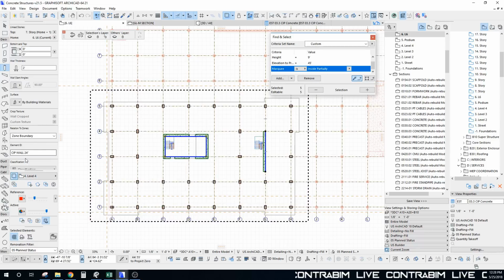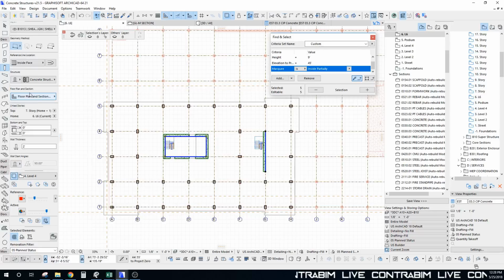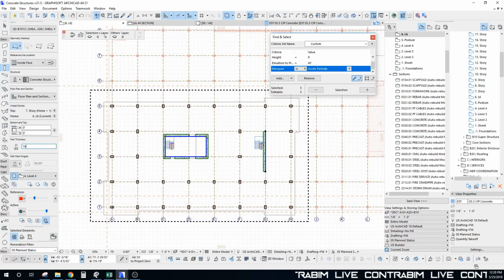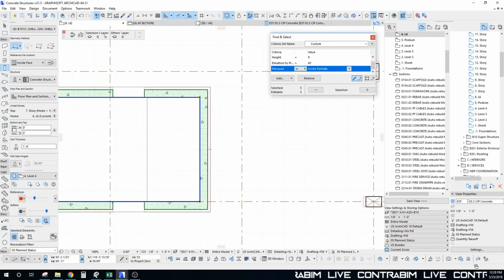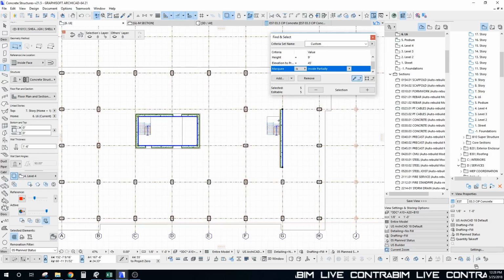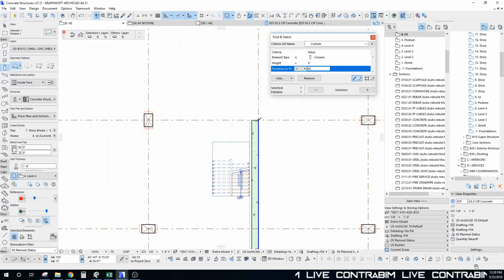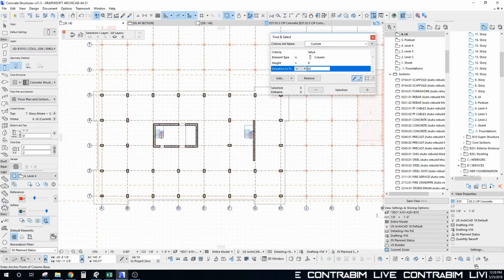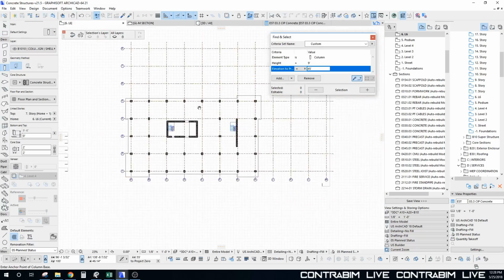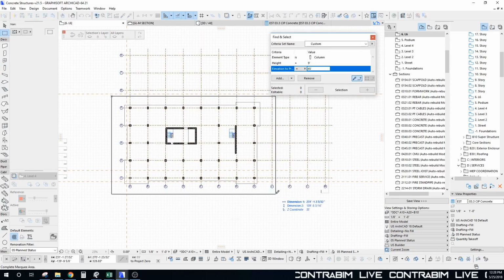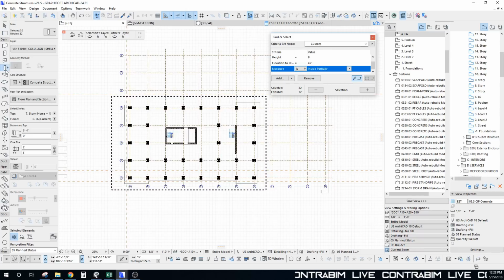These two core walls, maybe I'll just take them to 18 inches and adjust the width there. And so we can see our transition because we have our trace reference turned on. And this one here could probably, because our stairs are on the other side, have this on the wrong side. So I'm going to flip it and keep that core wall on the stairwell side.